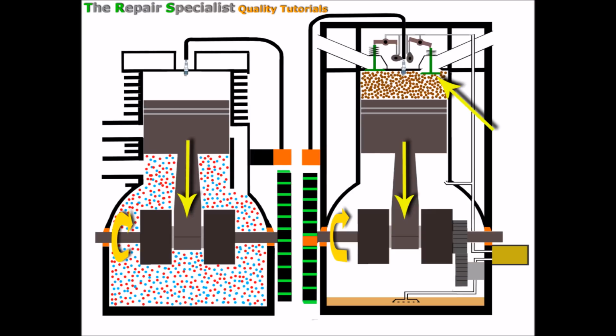So when the piston's on its way back down, we find here that the exhaust valve opens just slightly. And although at this point that might seem a little premature because the piston isn't yet coming back up and forcing the fumes out, the reason it actually does that is to allow some air to come in from the exhaust side, which is vital because if there wasn't, the piston wouldn't be able to travel down properly because there would be a vacuum there. And at the same time, a nice flow of fresh air coming into those exhaust fumes helps to dilute them so that when the piston rises again, all the exhaust gases can be flushed out that bit better.